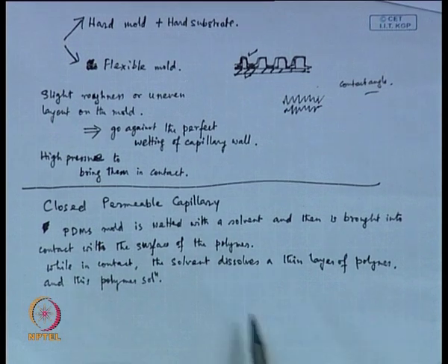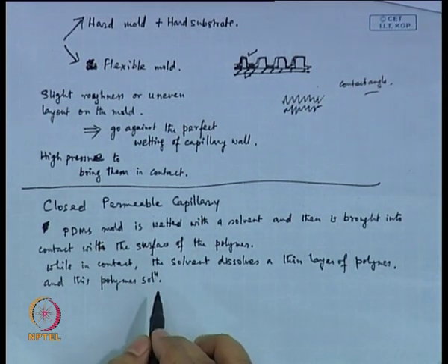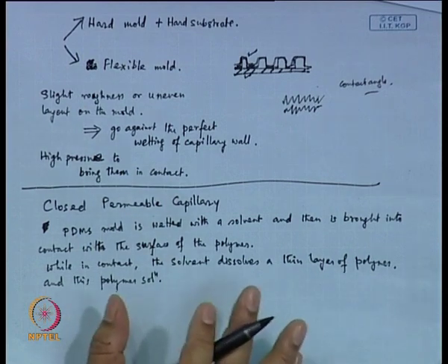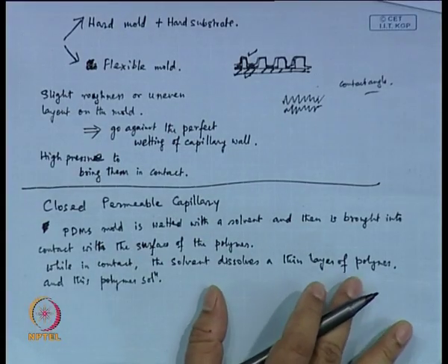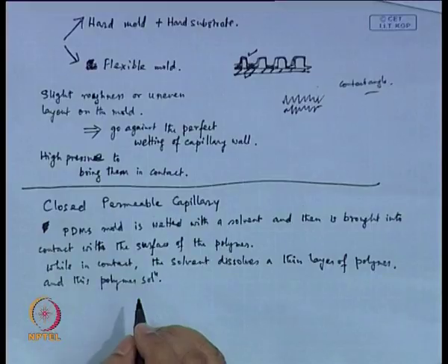So, basically this solvent dissolves a thin layer of polymer and this polymer solution would now be traveling to the nook and cranny of the features by capillary action. So, this is a possibility.